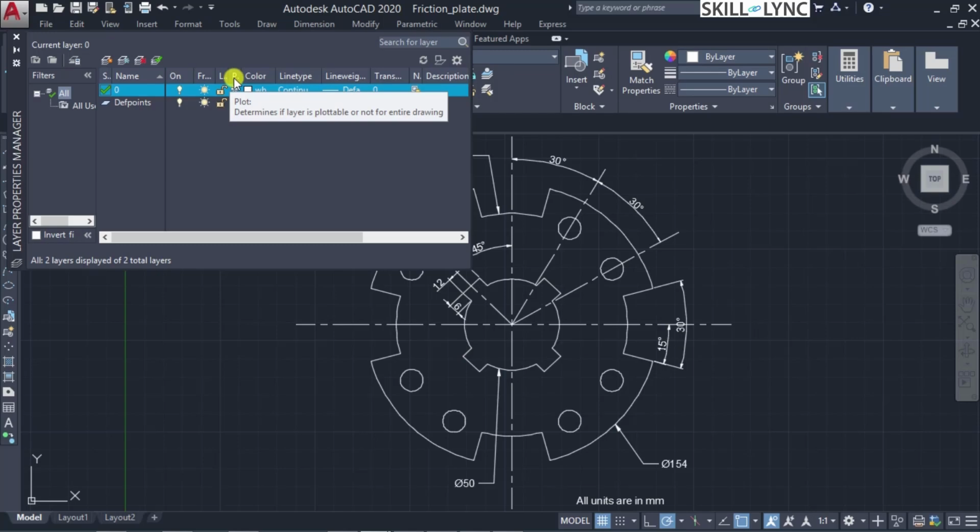It means that certain information pertaining only to the drawing can be put in those layers and may not be taken for plotting. So which type of layers should be taken in for plotting or not? Categorically, you can apply different properties to the different layers. Next we have colors based on the drawing, so that whatever is default as specified, you can modify the property as a whole, then the line type and also the line weight.